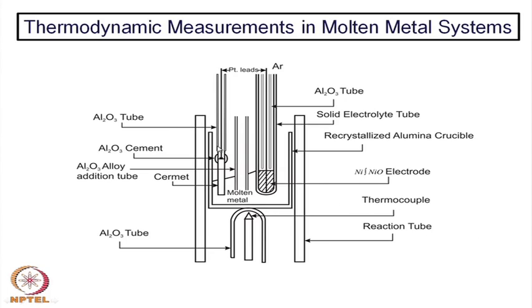In addition, coming back to this picture, in addition to the measurement of oxygen concentration in gaseous systems, one can utilize zirconia sensors for liquid systems also. Many of the metals do have some dissolved oxygen, or sometimes there are oxides present in the metal. So there is an oxygen potential, it may be large, it may be small, but measurement of oxygen concentration in molten metals or molten alloys is also of very great interest.